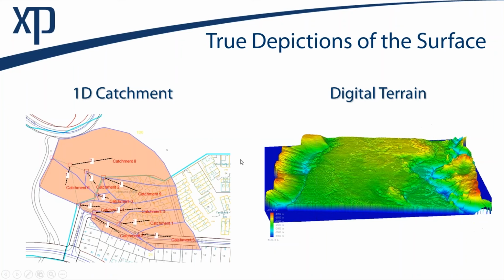In 2D, the delineation of the terrain is precise. We just use the terrain model, right? And in addition, we can use additional data to really dial in and give an accurate representation of the 2D surface. If I have a shapefile that contains street shapes, and I've got another shapefile that contains pasture land and another one that contains building polygons and so on and so forth, I can assign infiltration models and evaporation models or what have you based on the geographic location that's represented in the shapefile. So I can be very precise as to where I'm going to have impervious soil. It's where my streets are, relative to a residential yard or a pasture.